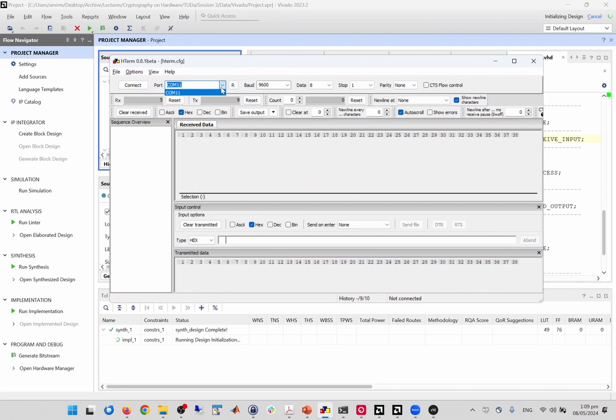It's not connected, so the COM port 11 that you see here is not of this board. Then we need to change it, and you will see that you get another COM port here. Or you look at, for example, the device manager of Windows, and you identify which COM port your board has. You go to the device manager, you disconnect it, you see one COM port is gone, and you connect it, and then one COM port shows up. And then, of course, the number of the COM port you can change on your computer.